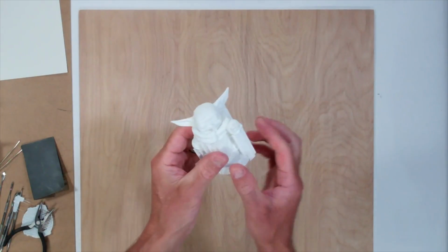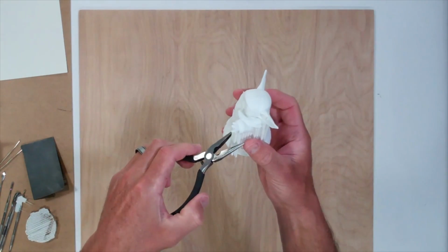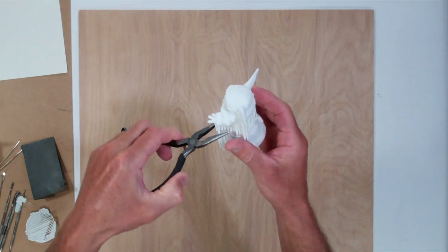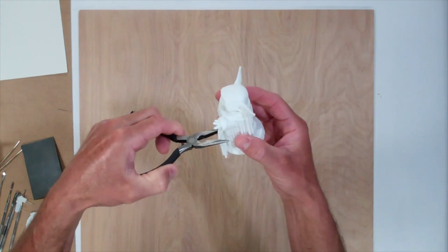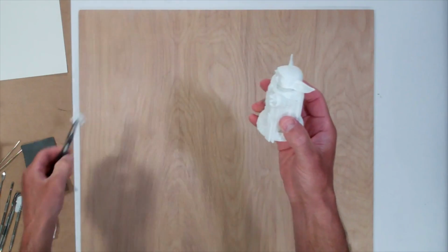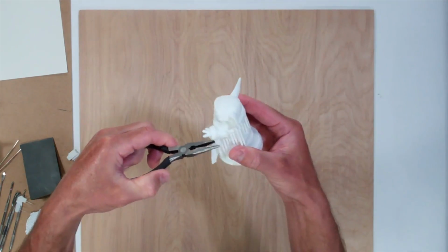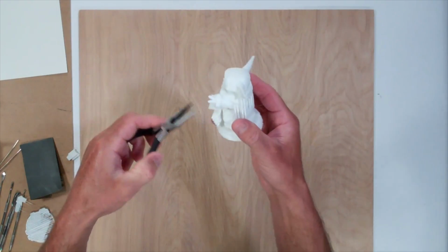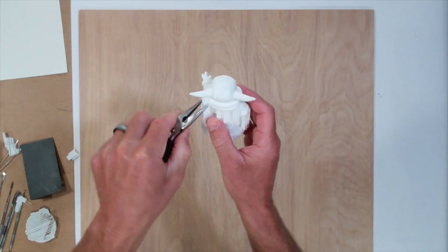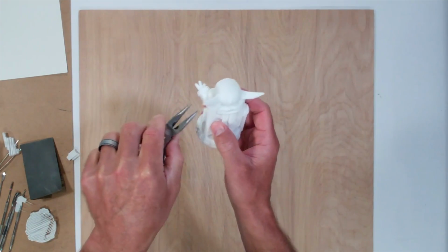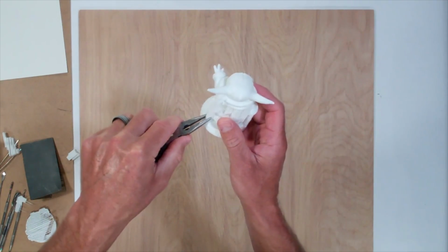The next step is to take off all of the supports. Be very careful doing that. When you're pulling off supports, it's best to just grab large areas and wiggle it a little bit. If you don't and you just go ripping this stuff off, you're probably going to take parts of your model off. So take your time, wiggle those free, and the large chunks of them should come off pretty easy. Again, be very, very careful with small, delicate areas of your model so that you don't bust those off.